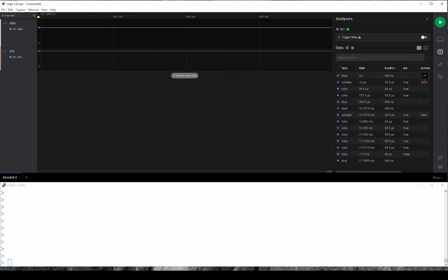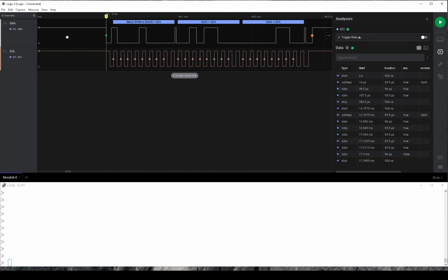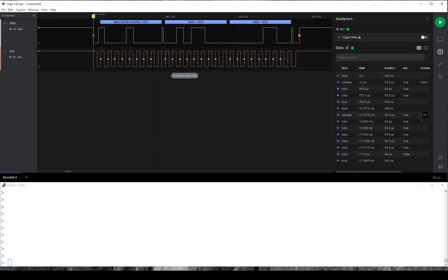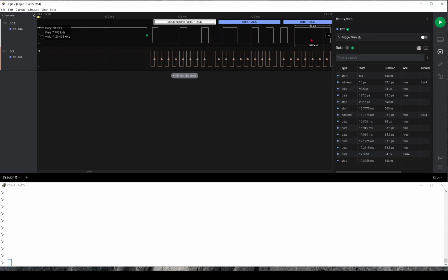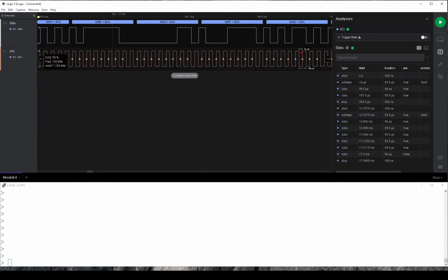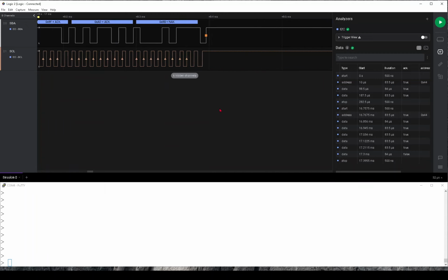So we've seen this same thing in the I2C demo, but let's just look quickly at these signals. There is the write, and here is the read, and nothing too special about those. Now what I'd like to do is reduce the amount of time that we wait before we read the measurement. As you might remember, if you try to read the measurement result too soon, we have chosen an option where the chip will stretch the clock.